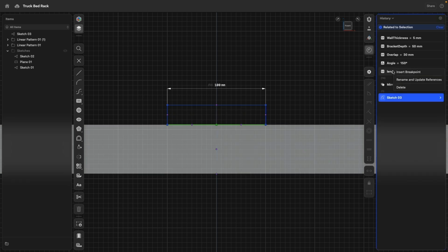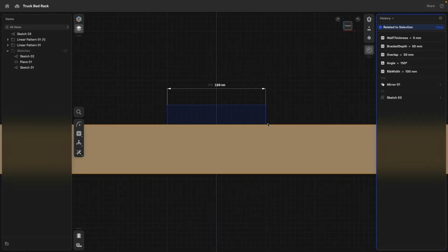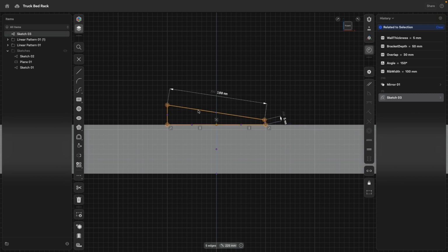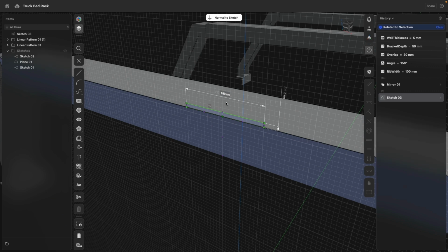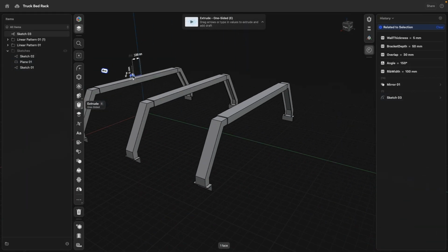Very good. And I can call this one rib width, for example. And then the height, that should be normal thickness. Now it's all constructed out of the same material thickness. Selecting everything, say horizontal, vertical constraint, and you see now the sketch is green, perfectly constrained. And you also see here now with fx, that always means that this number is actually the result of an expression or a single variable. I can select that sketch profile, extrude this out, and then move it directly onto the end of this face. Beautiful.